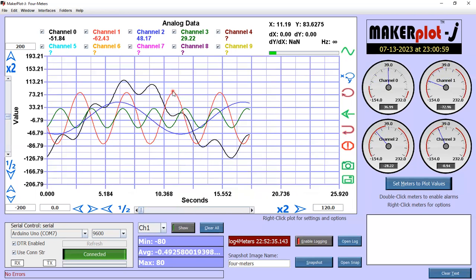But if I right click and drag, you get a red line there. That will tell me the distance between those on the X axis, or on the Y axis. Okay, be able to get those distances. And also it will calculate the slope of that line. So it's got a slope of minus 187.3, steeper, and that's dy over dx up here. Whereas the distance is dx, x distance, y distance, and then the slope.